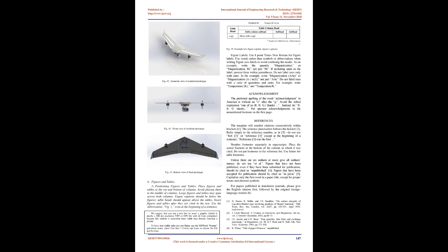Here analysis is only performed on the spars as these structures support all the loads. A static structural analysis is performed on them and the material chosen is mentioned below. Boundary conditions. The spars run from one end of the body to the tip of the wing, i.e. the tip chord. The center of gravity rests within the body, i.e. most of the weight rests within this structure. As a result, the body is treated as a fixed support while the other end is treated as a free end. This is a cantilever beam and accordingly analysis is performed on them.